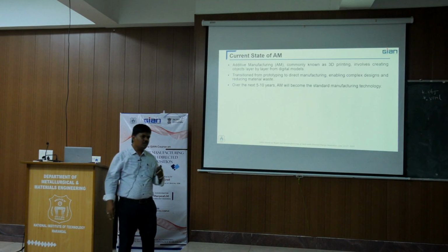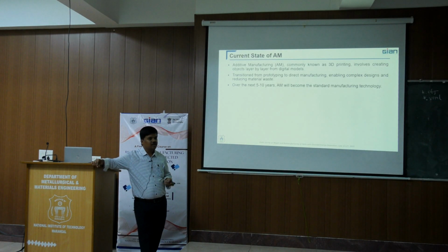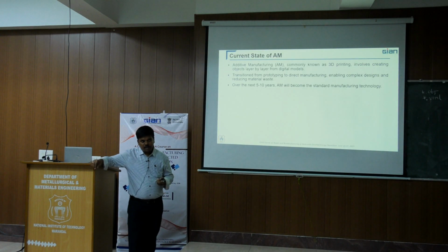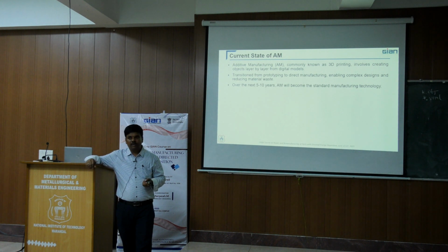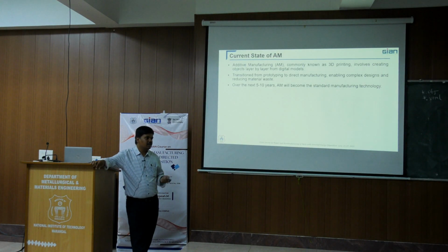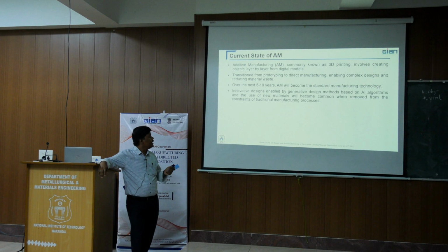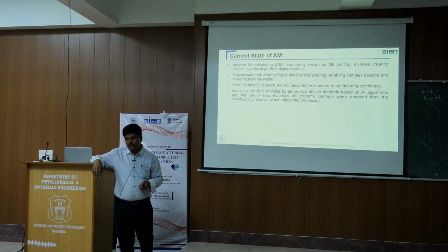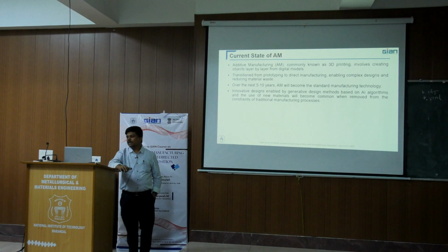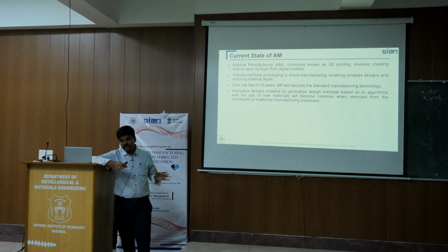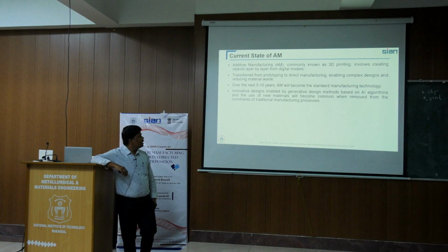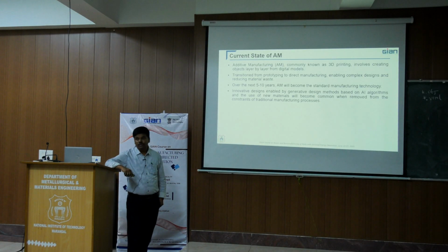Titanium 64 is more biocompatible, and because of that, even 316L is also used in applications such as screws or plates. Especially for implants, they use titanium 64, and grade 23 is biocompatible. Innovative designs, like generative designs, are also enabled. These are topologically optimized designs, generative designs based on artificial intelligence algorithms, which we can make use of for new materials.